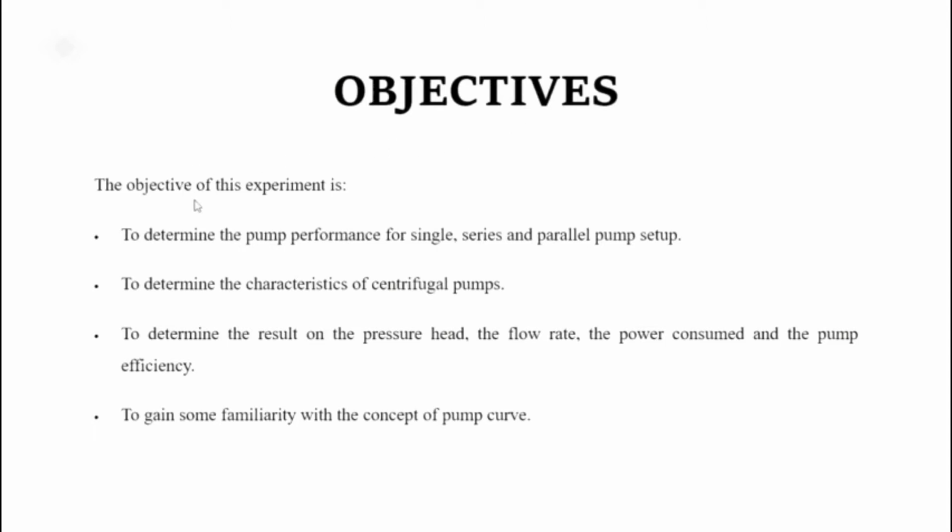So our objective is to determine the pump performance for single, series, and parallel pump setups. And next, we want to determine the characteristics of a centrifugal pump. And next is the result. We want to determine the result on the pressure head, the flow rate, the power consumed, and also the pump efficiency. And lastly, we want to gain some familiarity with the concept of the pump curve.